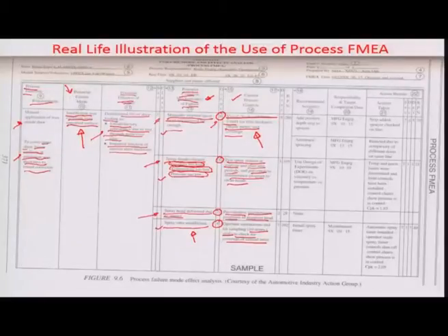And again, the quality in charge who looks at this defect tree sees the various levels of detectability with the current process controls and rates about 50% to step 1, that is the visual check for film thickness. So about 50% of the times you can detect the manually inserted spray head not inserted far enough through just a visual check on the film thickness. About 30% of the times you can detect whether the spray heads are clogged through the test spray pattern control point, which is already there in the system.